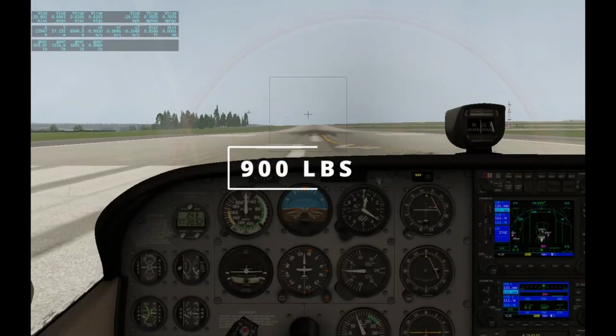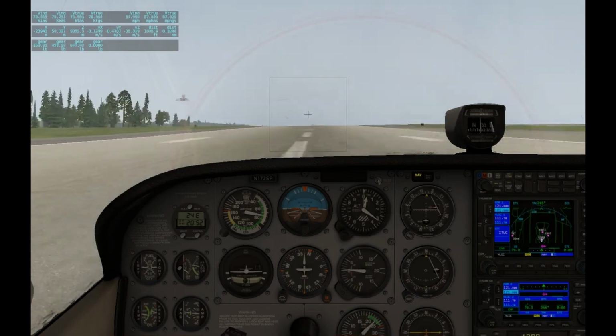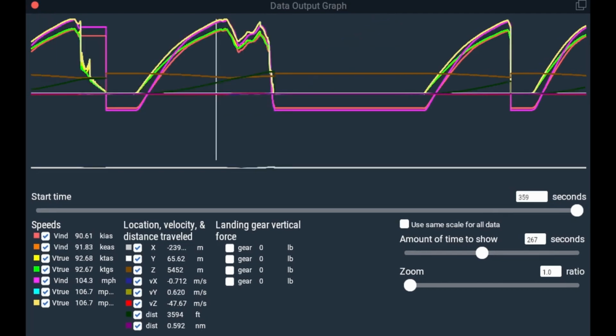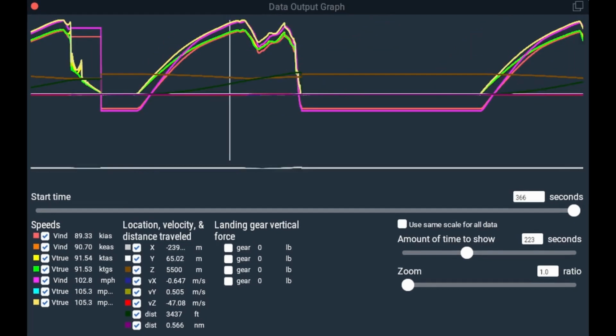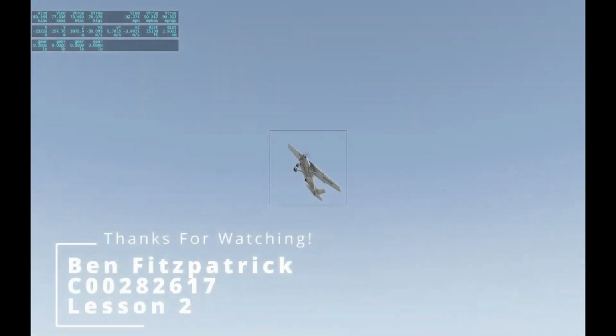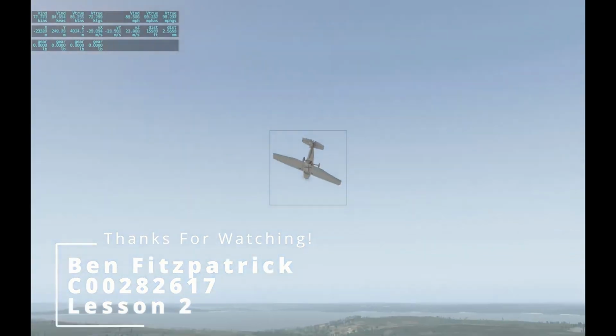And eventually we did a 900 pound payload weight test, where we had a takeoff range of 2,834 feet to 3,594 feet, by far the longest takeoff distance. The purpose of lesson 2 is to provide a key understanding of how weight affects an aircraft, and how payload weight and aircraft weight can affect the overall takeoff distance necessary to become airborne.